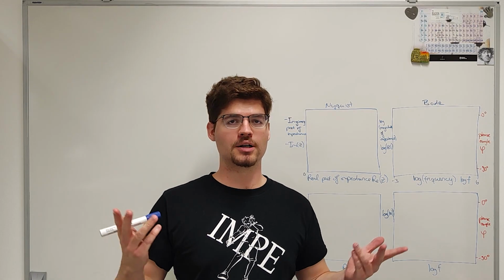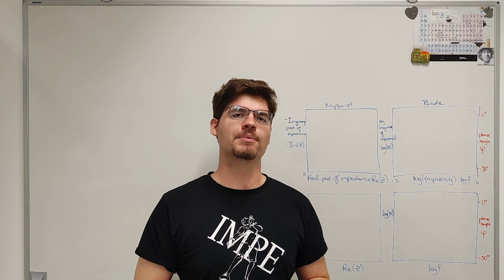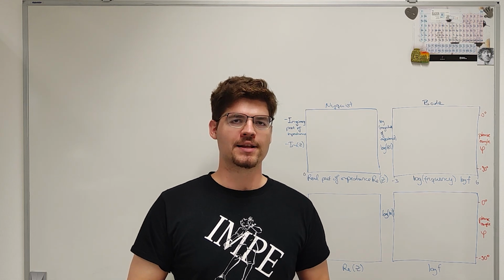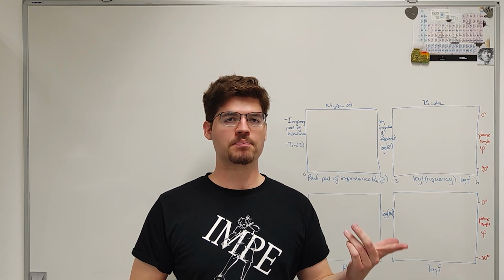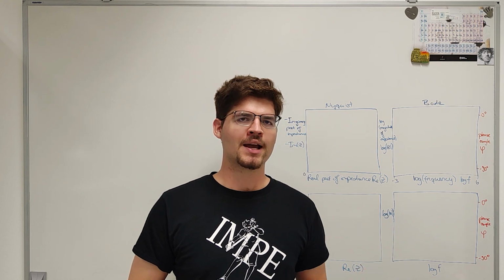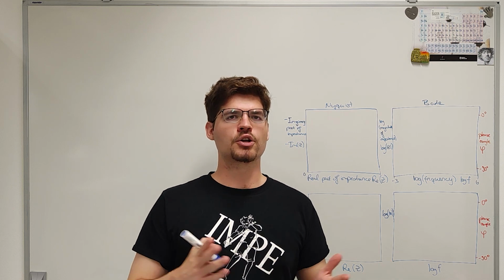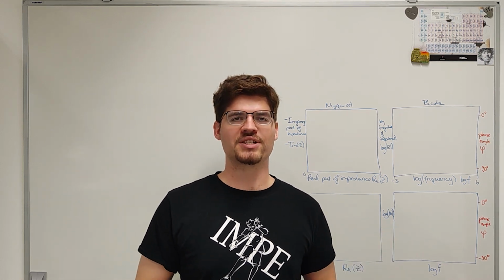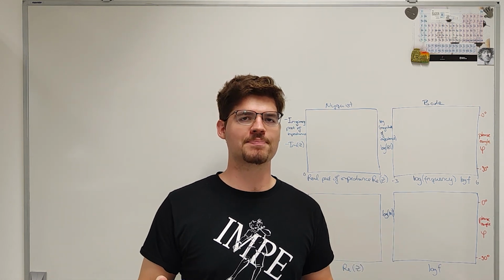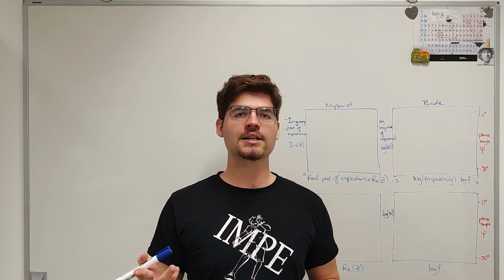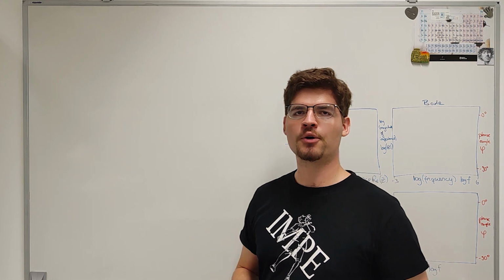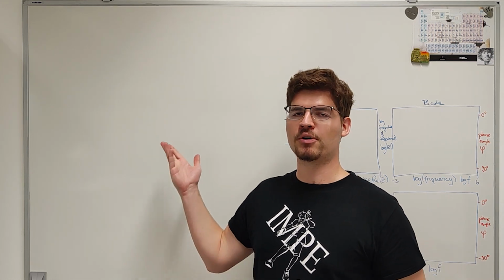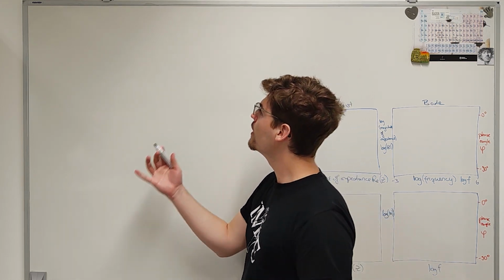Welcome back to our video about what is an electrochemical impedance spectrum. The last time we looked at the spectra of a resistor, a capacitor, and both of these elements in series. However, sometimes these are not all the circuits that we need to represent what goes on in an electrochemical system. Sometimes parallel circuits are needed, and this is what we want to look at today. So first, let me introduce you to how the impedance of a parallel circuit is calculated.